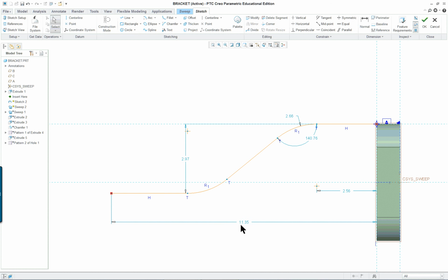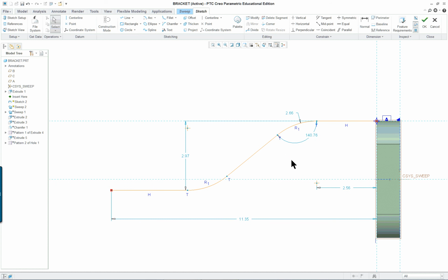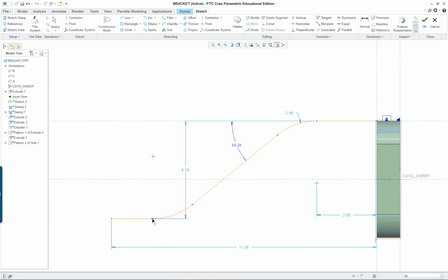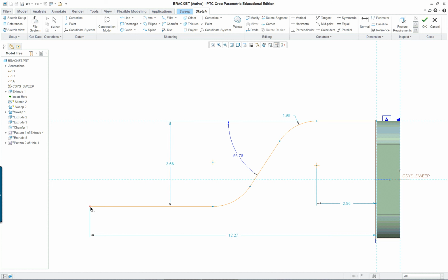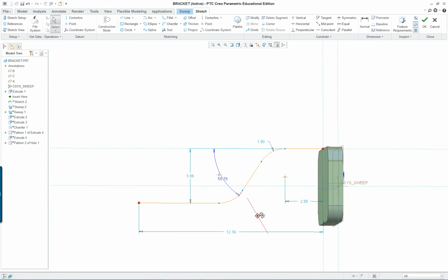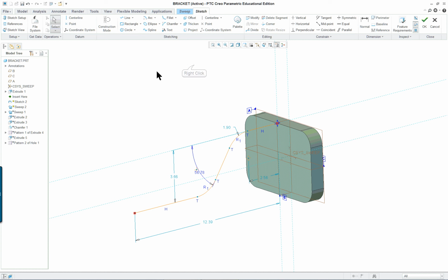If you can't get the cursor to select something properly by hitting your right mouse button, you can come up over here and select one by one. This actually has a similar scheme for dimensioning, but we're using this internal angle instead. I think I'm closer to 60 degrees. Again, I'm not going to make it exactly correct, just something similar. You go by the dimensions in the book, of course.